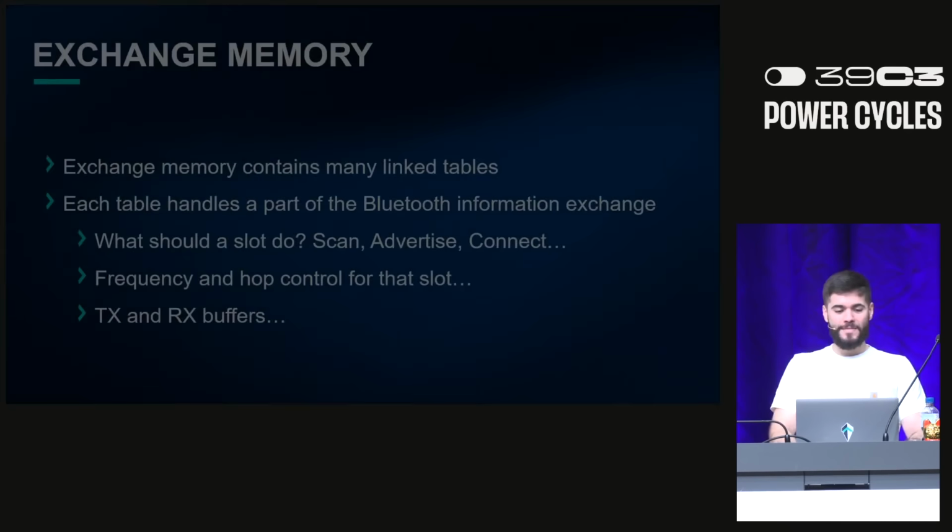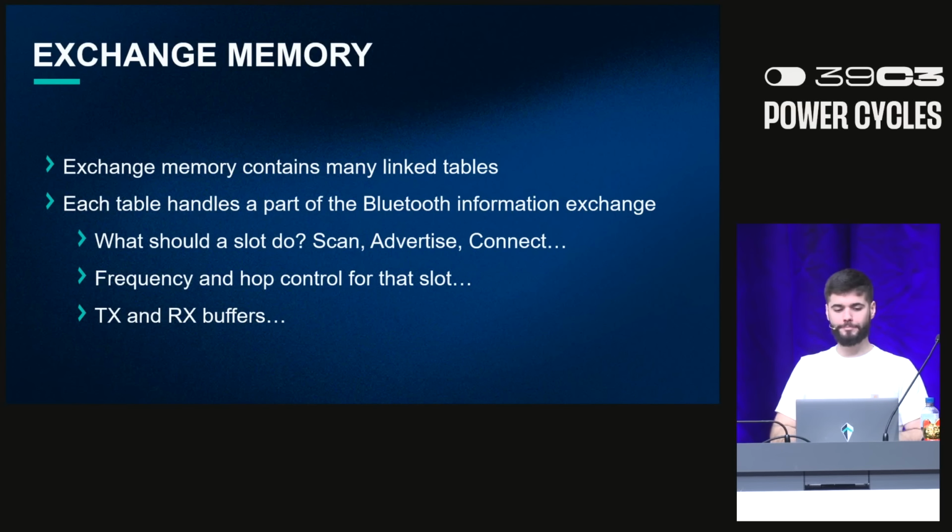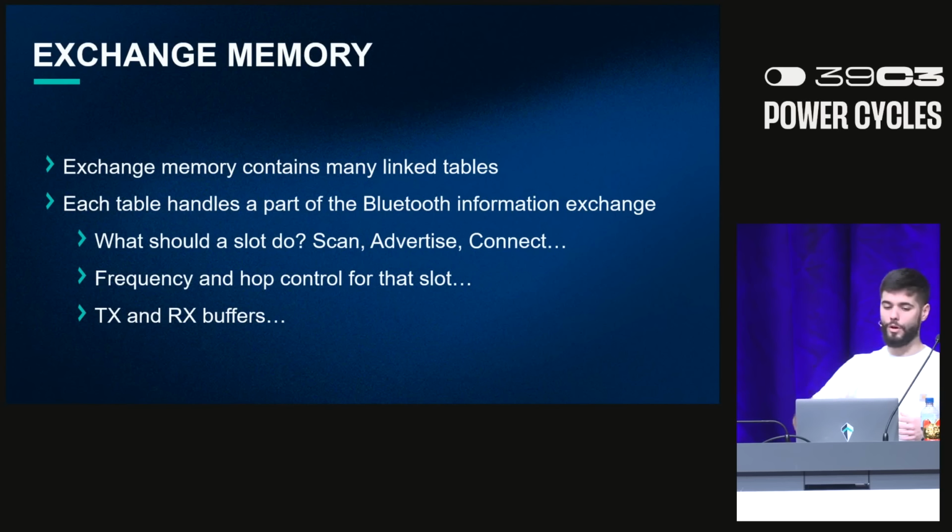And yeah, the second memory region we were talking about is this shared memory region. This shared RAM region contains a lot of linked tables. This is quite a big region, okay? And each table handles some part of the Bluetooth information exchange with other devices.